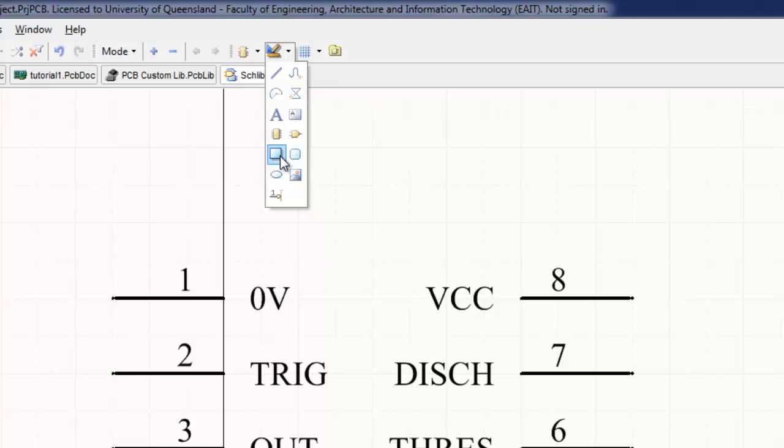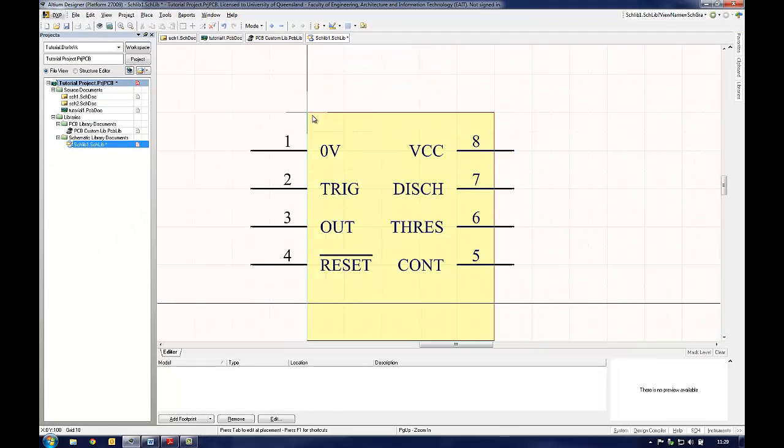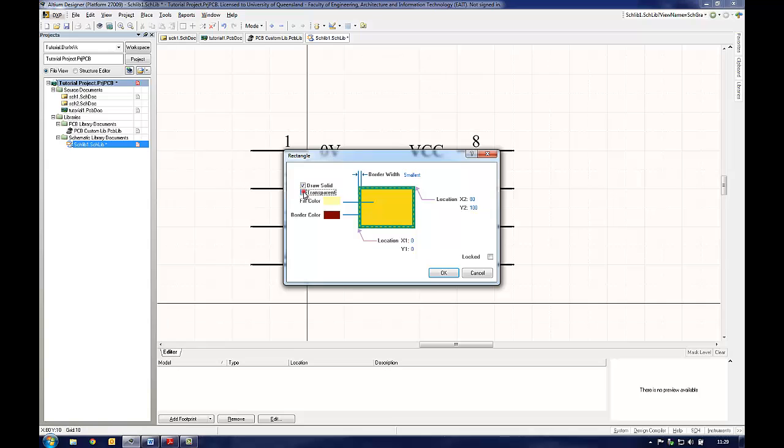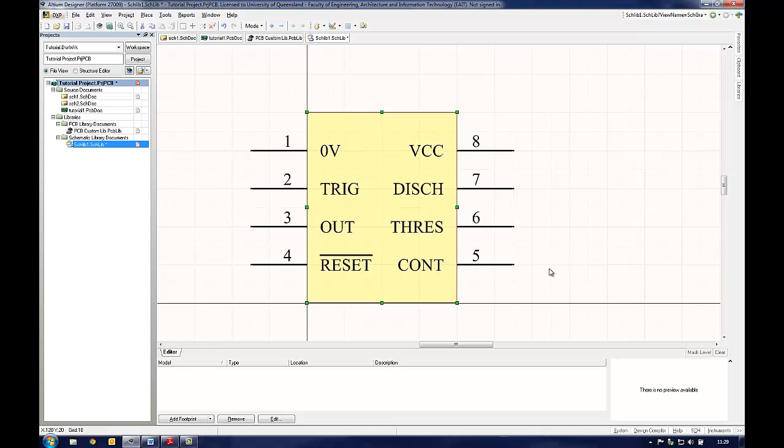To draw this using Altium, select Place Rectangle from the Drawing Tools menu located on the toolbar. The user is required to select the diagonally opposite corner boundaries of the IC. As with any item drawn in Altium, the user can double-click this rectangle to edit its properties. The user can also place lines, freeform polygons, place text, place arcs, and many other shapes and symbols.